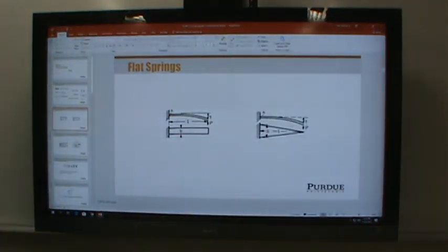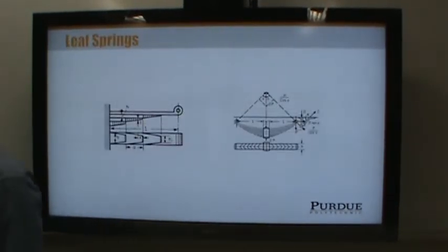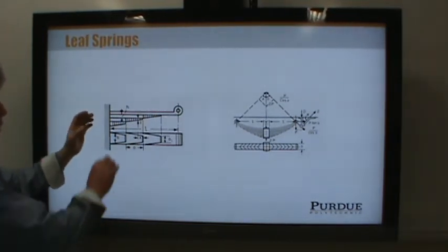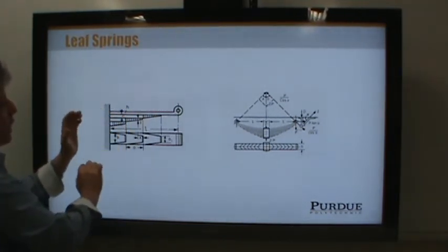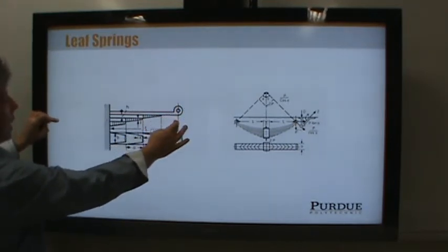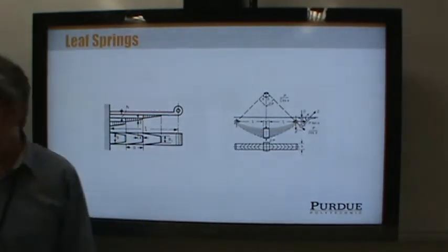But anyway, so we're talking about springs and the fact that leaf springs, flat springs, can be made to be nonlinear if you wish pretty easily. Now, a leaf spring is very different from a flat spring. It's like a flat spring, but basically it's like one cantilevered to the wall, right? Because there's no rotation here in the center that's allowed because you've got a mirror image on the other side. And so a leaf spring, because of the way it's supported, is a lot like a flat spring, but you kind of get two springs for the price of one out of it.